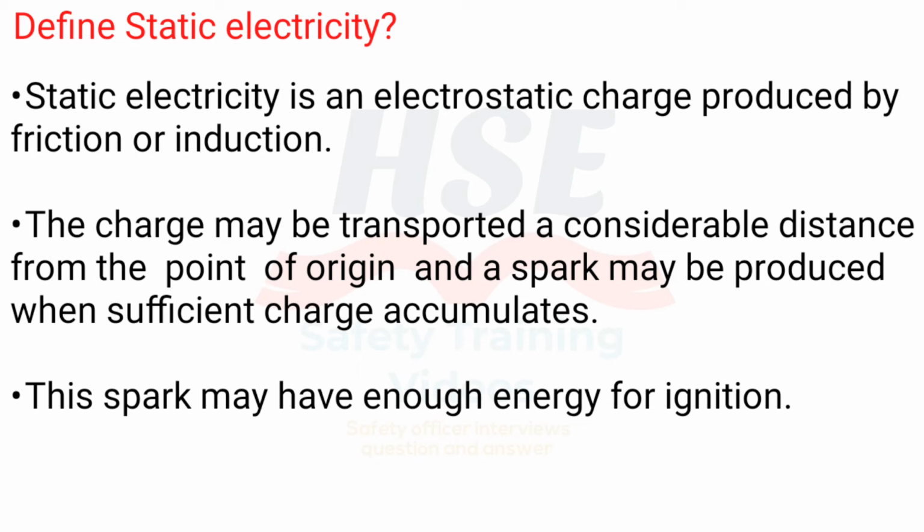Define static electricity. Static electricity is an electrostatic charge produced by friction or induction. The charge may be transported a considerable distance from the point of origin and a spark may be produced when sufficient charge accumulates. This spark may have enough energy for ignition.